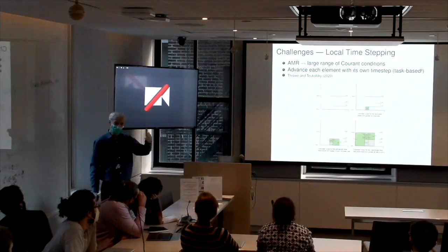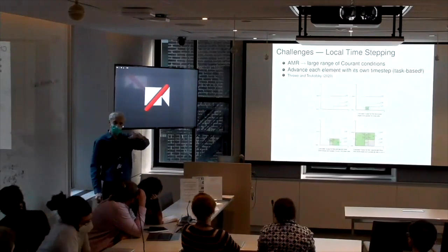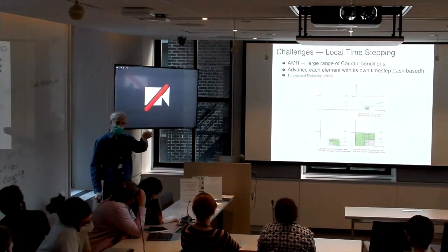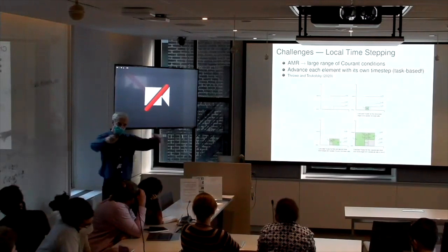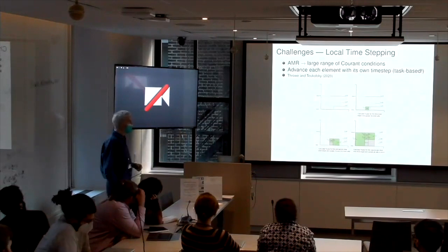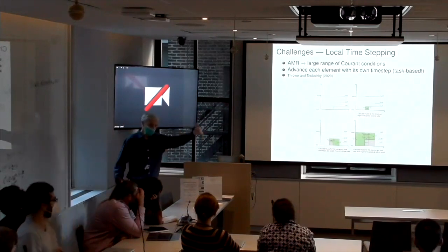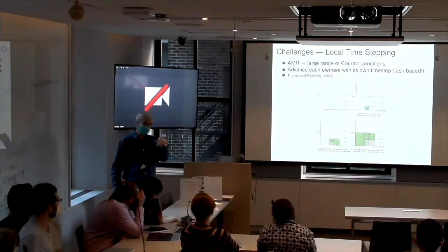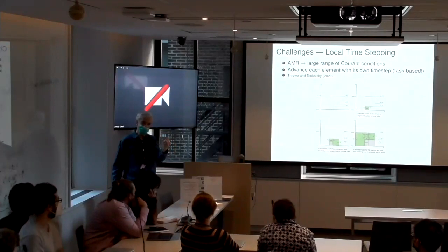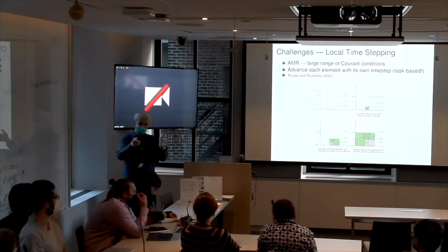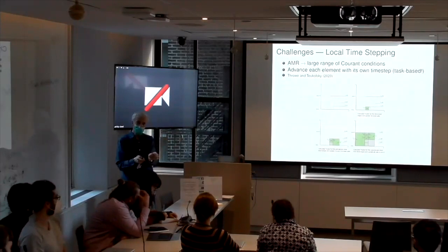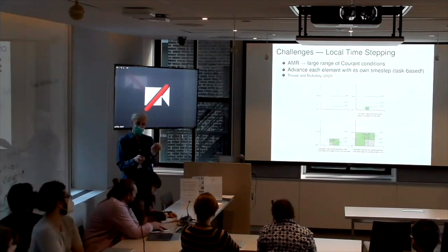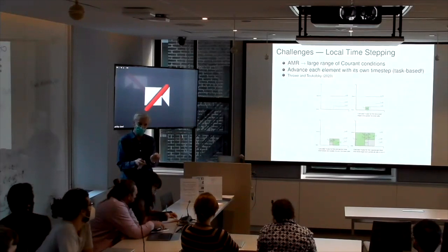Now, I mentioned adaptive mesh refinement, right? You want to use fine grids where things are changing rapidly, and coarser grids where you can afford to. But if you're doing explicit time stepping, you have this Courant condition to worry about. There's a minimum delta t, which is in order of magnitude set by the delta x, the size of your spatial grid. So when you do adaptive mesh refinement, there's a smallest delta x, and there's therefore a smallest delta t that you have to use.